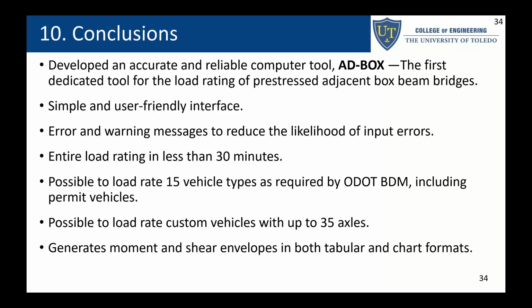If you are analyzing or load rating another bridge, not adjacent box beam bridges, you can still use AdBox to generate moment and shear envelopes, and you can use it in another software for any other type of bridge. So it's a general capability. And we also aim to facilitate learning the overall process. We are giving additional information, commentary. There is some text which comes up as you enter your input to facilitate learning the load rating process.